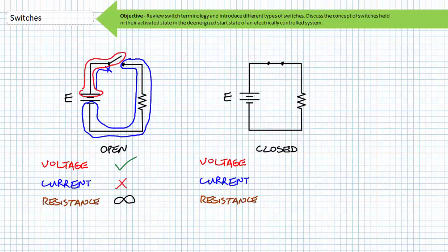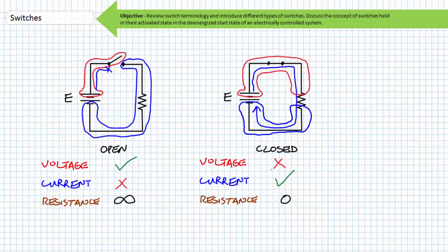In contrast, an ideal closed switch is idealized as a 0 ohm resistor, which will allow current to flow. Being idealized as a 0 ohm resistor, this closed switch should have no voltage drop across its two terminals. Although in practice, a real closed switch does present a measurably small amount of resistance and therefore might experience a tiny voltage drop, especially when carrying large amounts of current.